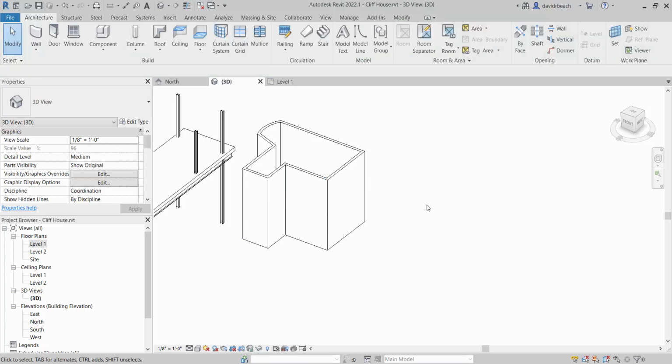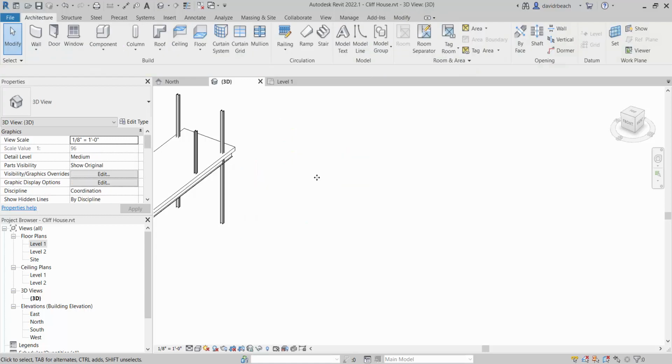However, those defaults are really not what we use very often, right? Because an 8-inch wall, like a standard 8-inch wall, even concrete block that we call an 8-inch block, it's 7 5/8, right? And those dimensions matter, okay? So let's get a little bit more precise and let's build sort of our own wall type.